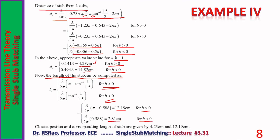So 4.23 cm is the desired location, and it happens for B more than 0, where the length of the stub is 12.19 cm. So the solution to this problem is a stub of length 12.19 cm, connected at a distance of 4.23 cm from the load to the main line.